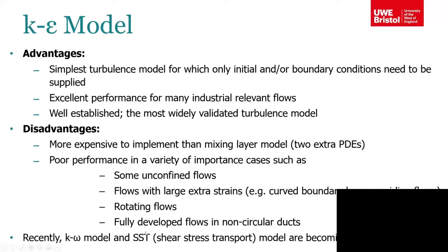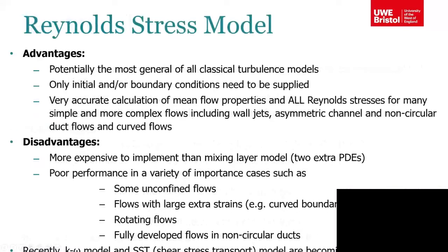What about even before, when we did the non-Newtonian flow? Did you still use K epsilon? We did it. You used SST, most of you. I'm not sure we did K epsilon, because you wanted to resolve the boundary layer, so you used SST, I think.